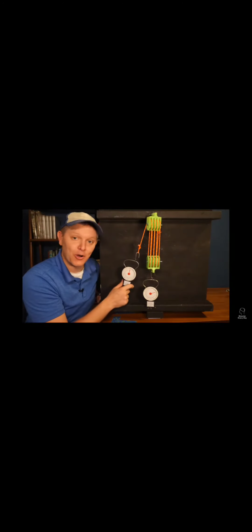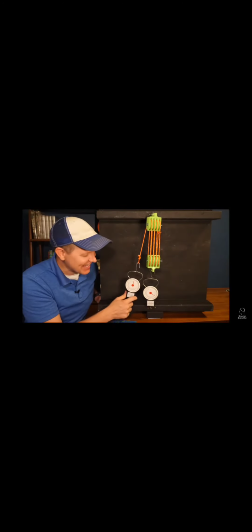How far do you think we can go with this? You think we can double it again? So now we have 2 blocks with 4 pulleys each, which if you count all those up, 1, 2, 3, 4, 5, 6, 7, 8, we have 8 ropes in tension on that block. So as I pull here, look at this. That's nuts. That is a little bit of force and a lot of output. That is some serious mechanical advantage. Look at this though. The ropes over close to me are moving a lot, but the ones over near you aren't moving as much. Let's break this thing apart again and see if we can understand what's happening.